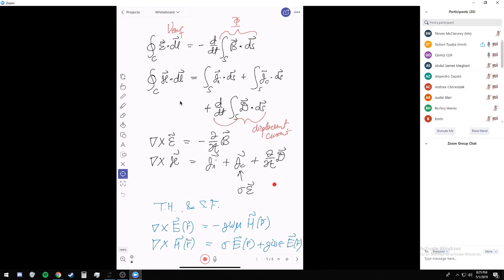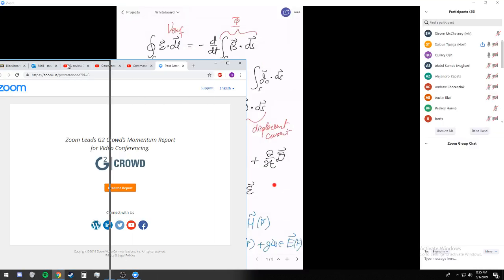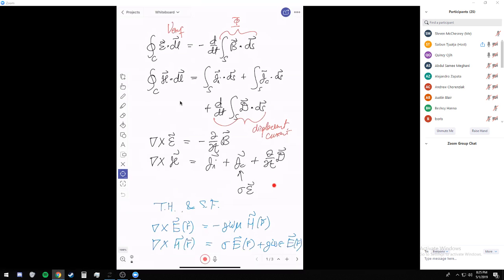The electric field is perpendicular to the two conductors, and the magnetic field is basically confined within the two conductors. So you know where they are, and where does it go? It follows your transmission line. For that kind of problem, we only have to worry about how far it is from the generator, how far it is from the load. Whereas now in chapter 7, we don't know, because it can be anywhere in space.